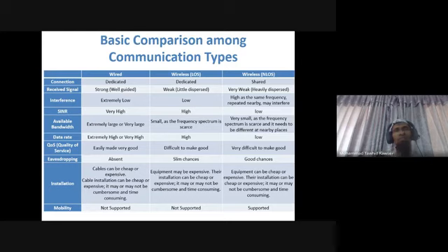And that's how in the system there will be many base stations interfering with each other. So when you are dispersing widely, there is no easy way to stop the interference. On one side you have a weaker desired signal, on the other side you have a stronger undesired signal, and the ratio of these two is SINR, the fourth point. Desired signal over undesired signal is called signal to interference plus noise ratio.